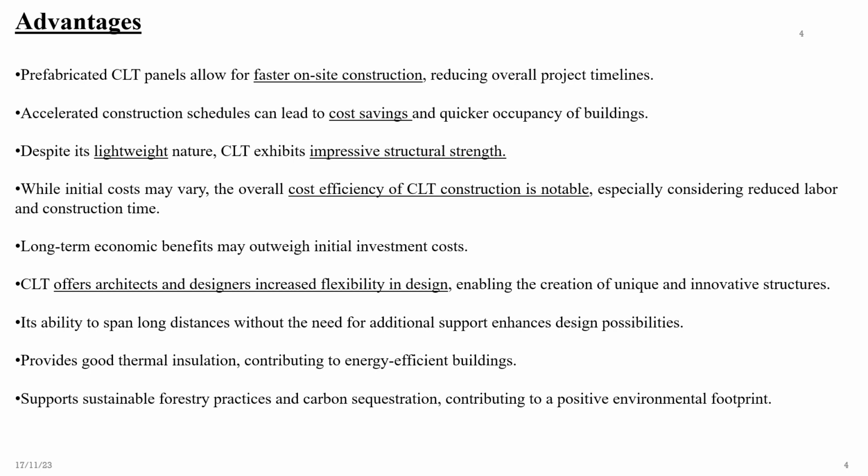Advantages. Prefabricated CLT panels allow for faster on-site construction, reducing overall project timelines. Accelerated construction schedules can lead to cost savings and quicker occupancy of buildings. Despite its lightweight nature, CLT exhibits impressive structural strength. While initial cost may vary, the overall cost efficiency of CLT construction is notable, especially considering reduced labor and construction time. Long-term economic benefits may outweigh initial investment costs.